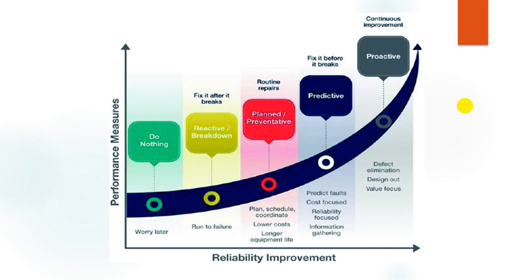The answer is we can. Then we need to define what this failure means. We consider failure, and it also differs from company to company, with certain rules. For example, if I say this failure or this stoppage, whether it's function or performance, costs us more than 10,000 USD, that is considered a failure. Whatever problem happens that causes us a loss of more than 10,000 USD is considered a failure.